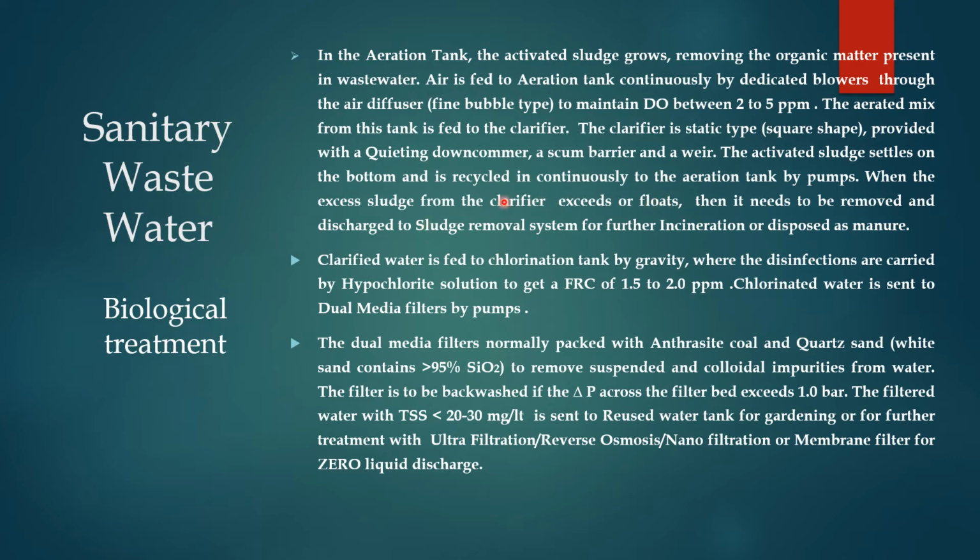And the aerated mixed water is fed to the next compartment called a clarifier. It is a static type, square-shaped clarifier tank, which is provided with a quietening downcomer.